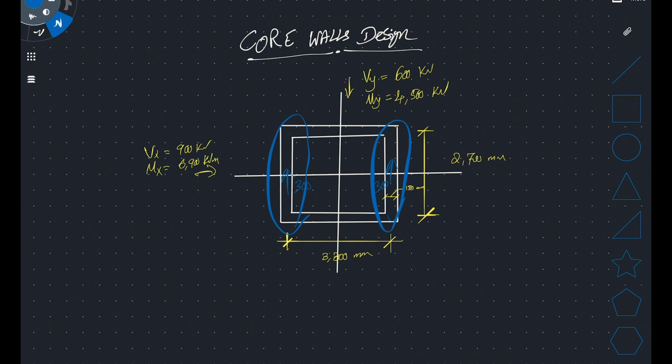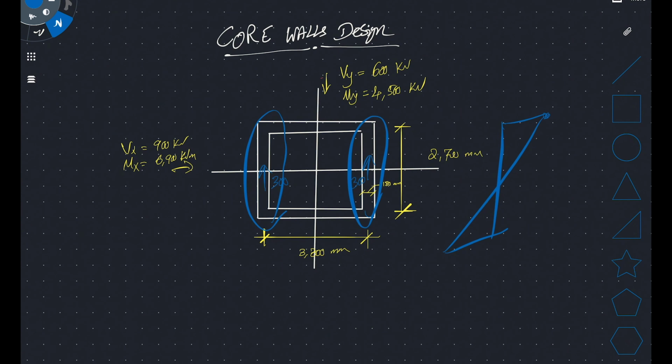Now in terms of the tension and compression, exactly like designing a steel hollow section or designing a concrete beam, you will have your stress looking something like this. You have a peak compression in this flange, peak tension in this flange, and a peak compression at the other flange at the bottom. So basically you've got these two returns resisting the shear, and the front and the back flanges resisting the flexural compression and tension stresses.